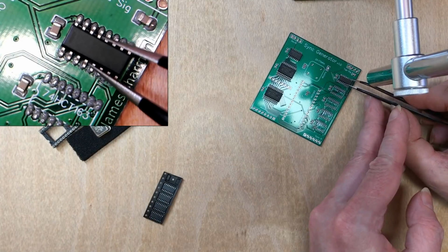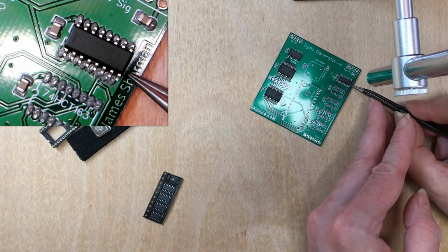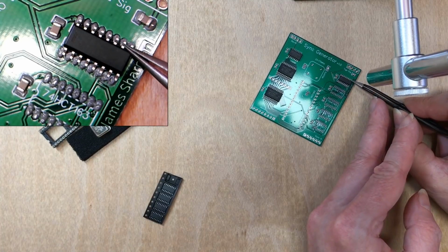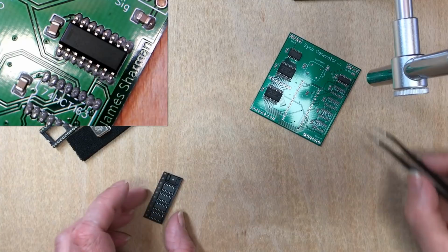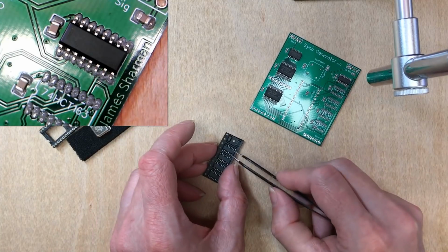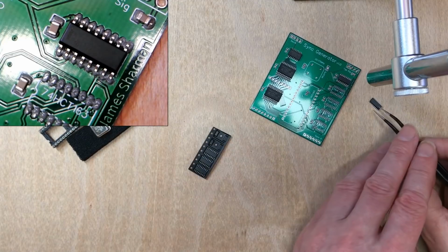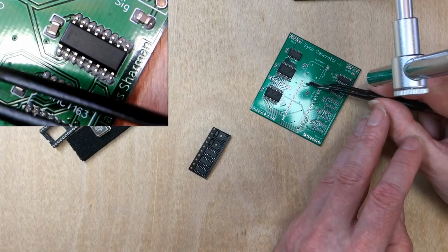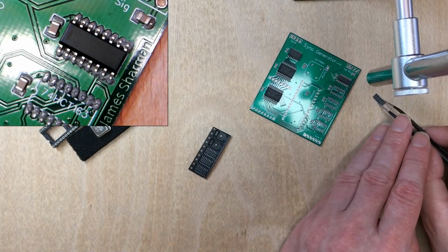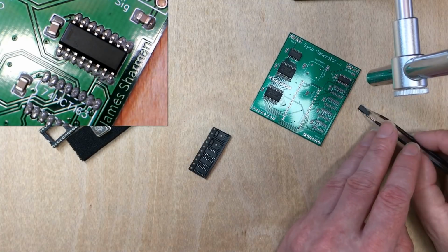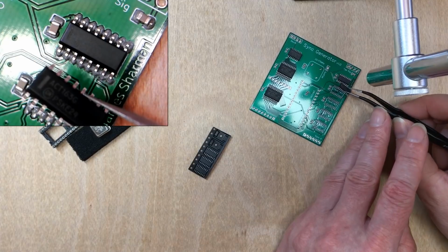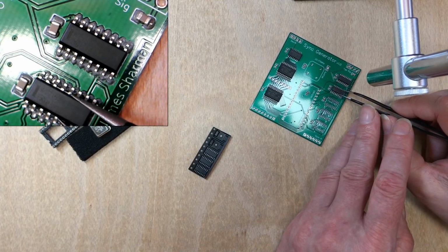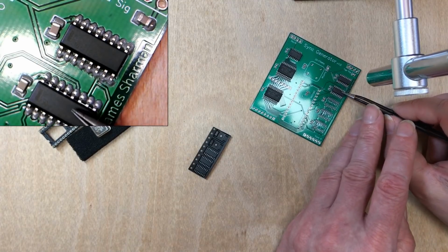These are actually ACT rather than HCT. And that's partially because when I went to order them, the HCT were out of stock. But I was planning to make this one up here an ACT because they do handle speed a bit better. And I'm thinking of using ACTs on anything that actually touches the 25 megahertz component. They're all pin compatible and very similar specifications. They're TTL compatible lines. They're just a bit faster.